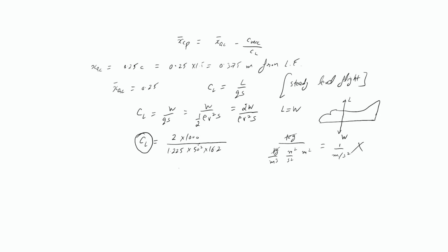The reason is you have to convert this unit from mass to weight, that is to Newton. You have to multiply this by 9.81. Most of the time students will make this mistake of not converting the units. So whenever you have any confusion about what unit to use, just write the units of the left hand side and right hand side of the equation. If they are matching, you can be sure you can use those expressions or units. If they are not, then definitely you have made some mistake. Most of the students commit mistakes here in converting to the desired unit.